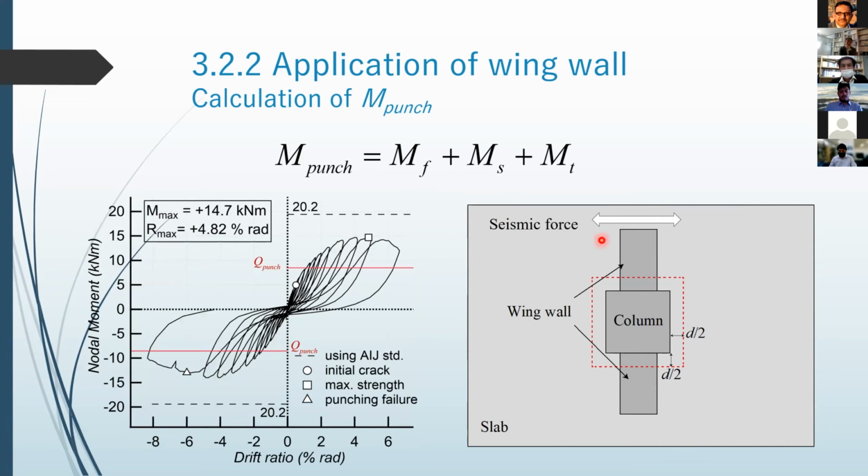In the case of the transverse direction, the red line is a little bit smaller than the experimental result, so it is a little bit conservative estimation. But if we apply this enlarged critical section for this case, it overestimates the experimental result. So at this moment, in this guideline, we decided to apply this critical section for conservative estimation.